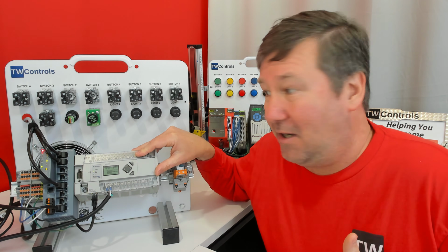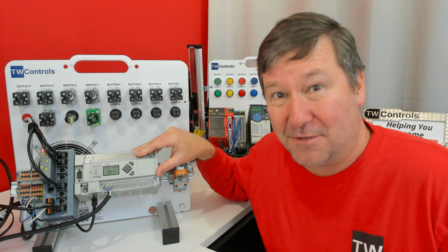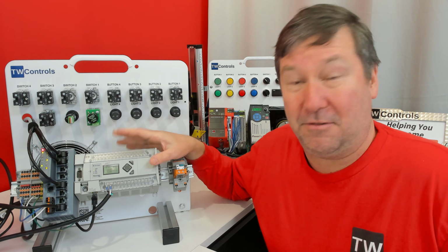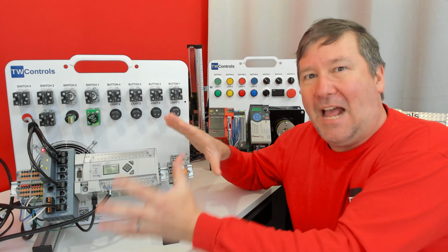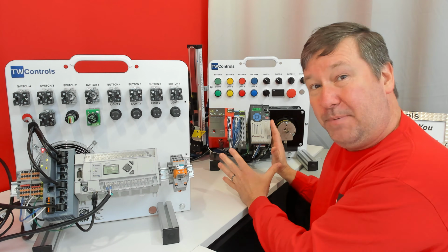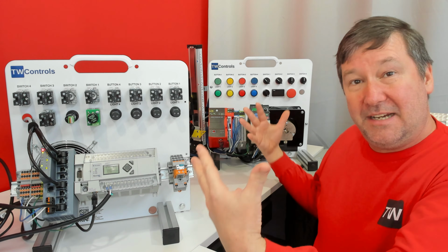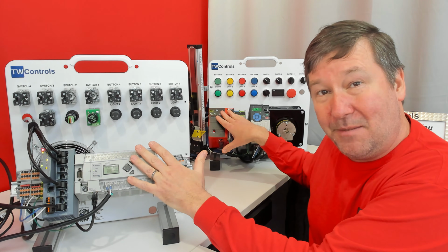The life of a PLC controlled piece of equipment is in the 20 to 30 year range. So we're going to be running into these for quite some time. Now, as we have a good piece of equipment out there and we need to integrate a new piece of equipment with it, we're going to need to communicate between those two. And even Allen Bradley to Allen Bradley, that can be tricky at times.